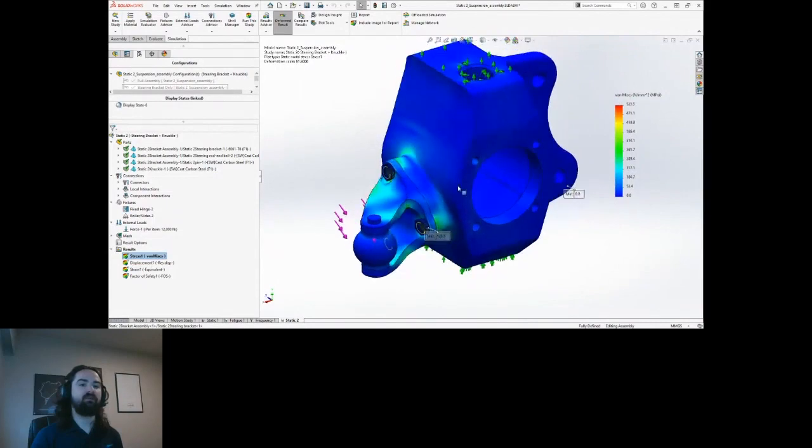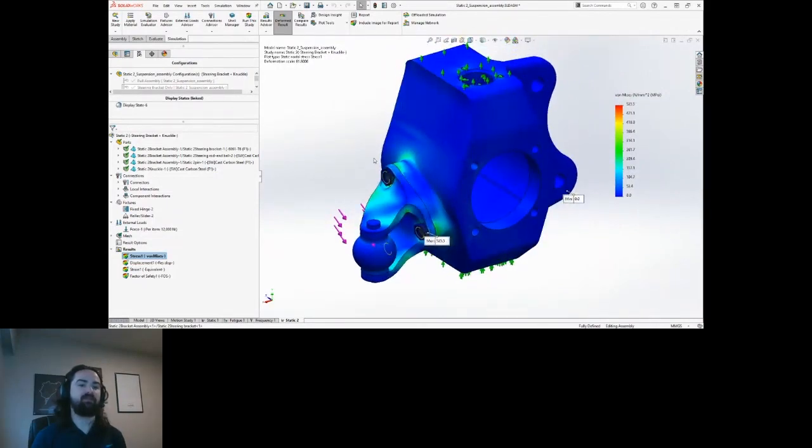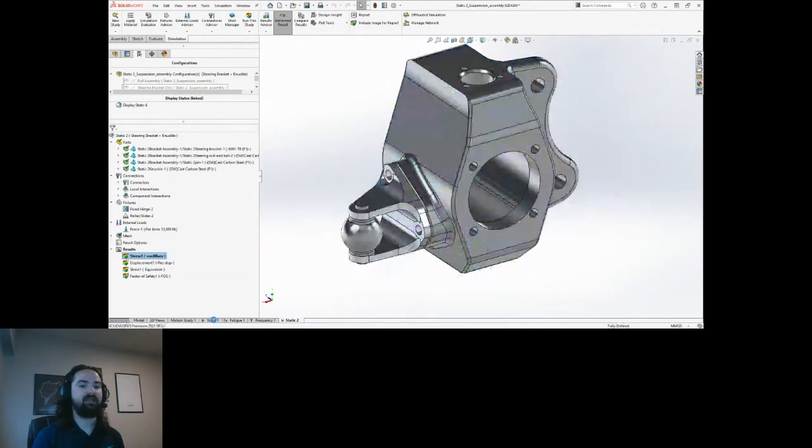So what I basically want to do is find the amount of stress seen in the static 2 study at the precise location of the maximum stress seen in the static 1 study. Due to the stress concentration at the bolt holes, however, the maximum flag we've been using to identify values thus far will not work as it's at the wrong location on the part.